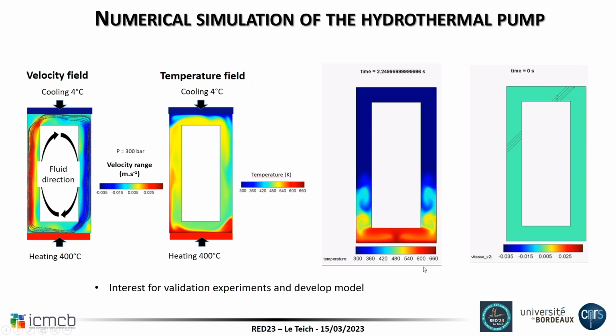You can see the heating waves that are starting, and then the fluid starts turning naturally, just by maintaining the temperature difference between the bottom and the top. Numerical studies are also interesting to predict fluid flow in porous media.